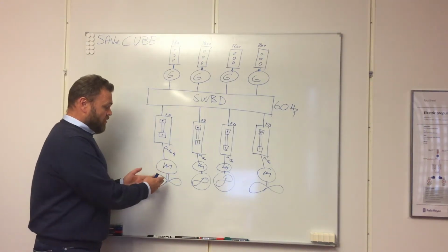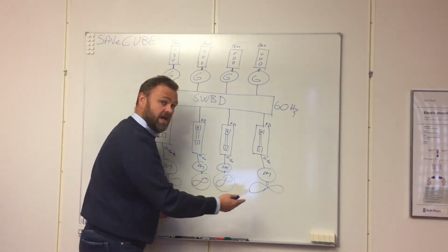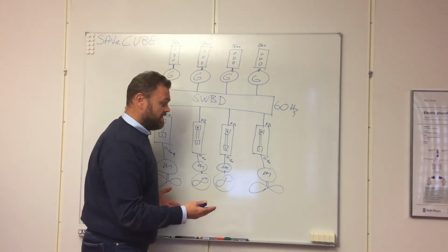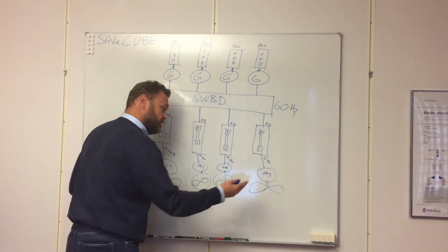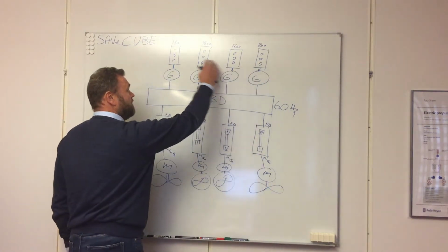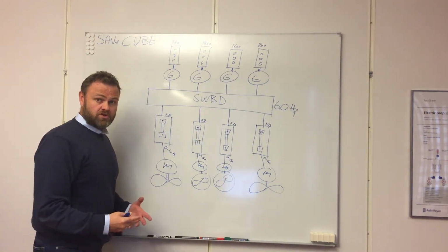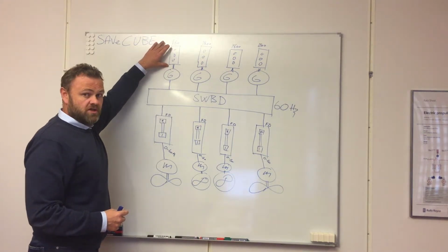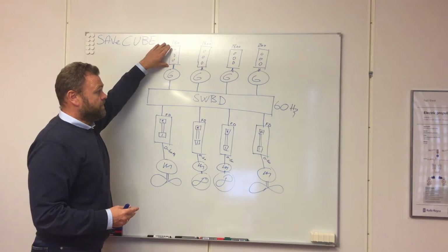Because if you can take away a couple of 100 kilowatts, maybe in the area of megawatts of losses for a big vessel, if you take away megawatts of losses from the propeller side, you will of course save megawatts of production, because you do not need to produce all those losses.